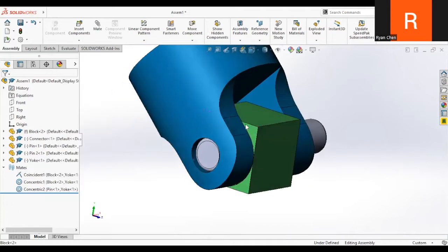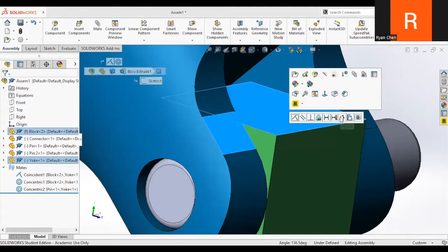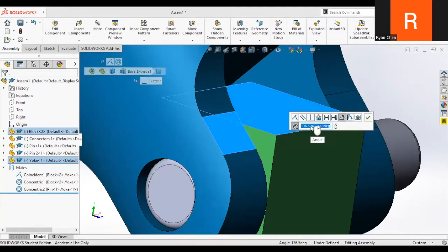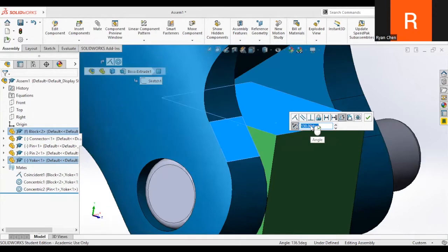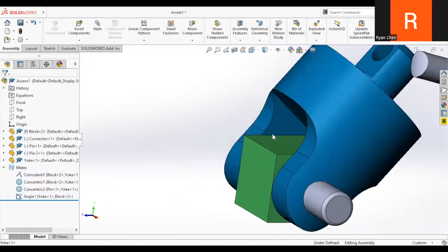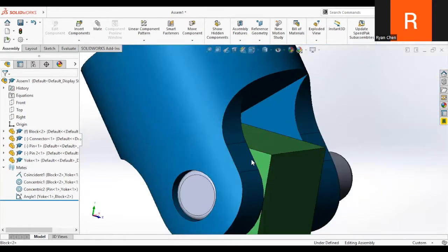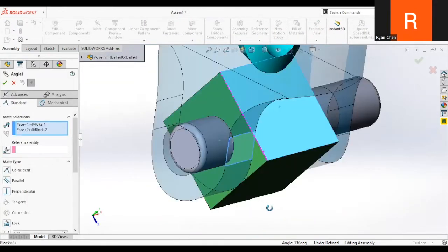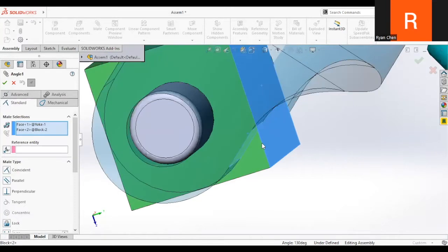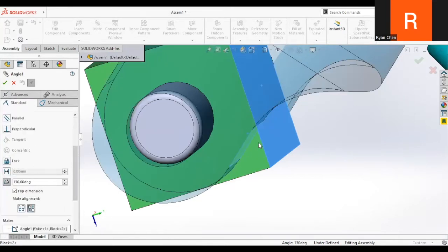We can also set things at an angle, but the angles can be super duper weird. So I can click these two. I can do something called angle, and I can set it to 130. It's very difficult because you might not know exactly what angle it's referring to, but usually it never goes greater than 180. So the best thing is that if it says it's 130, that means the angle right here would be, what number did I use? 130. So this angle would be 130 and this angle would be 50. It's kind of difficult to know what angle they're talking about.